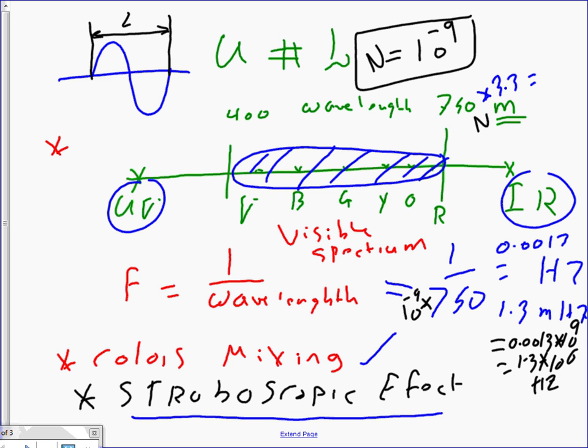The second thing, guys, is the stroboscope effect. That term they use in machines. Imagine that each one of you is a rotating machine, and you are powered by a 60 hertz fixture, running 60 hertz, one circuit. Because the frequency of the machine is 60, it rotates at 60, and the frequency of the light is 60. At a certain time, the saw that is rotating, because they're running at the same frequency, might look to your bare eye as not moving.